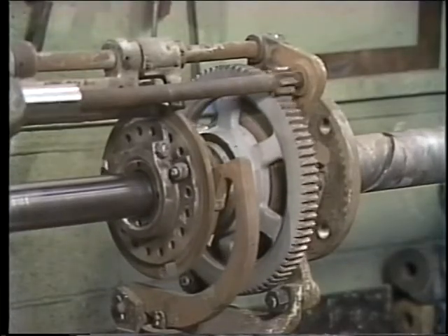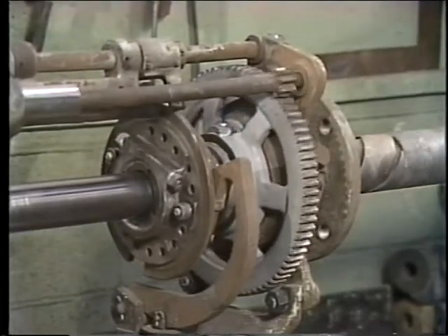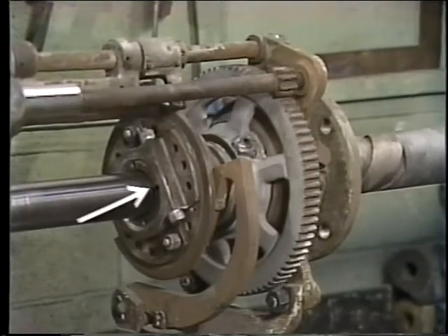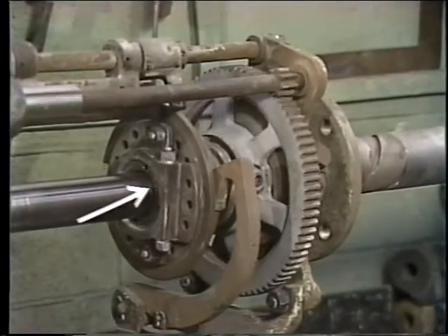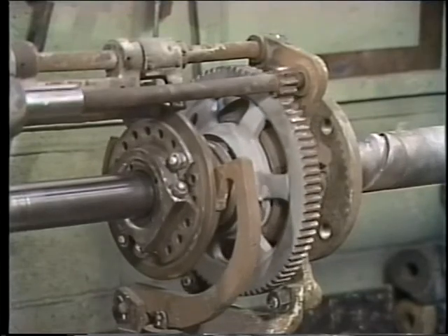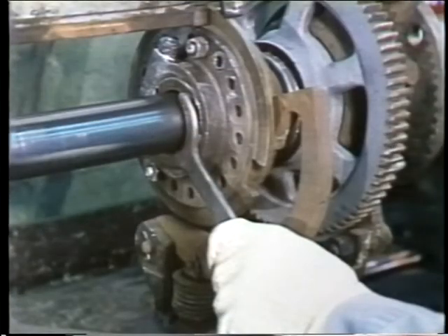On both stationary and retractable soot blowers, there is a packing gland at the back end of the element's tube over the feed tube. The packing can be adjusted by tightening the gland follower as necessary to minimize leakage of the blowing medium. A little later on, we'll be seeing how this can be done while the soot blower is in place, and we'll also look at repacking the element too.